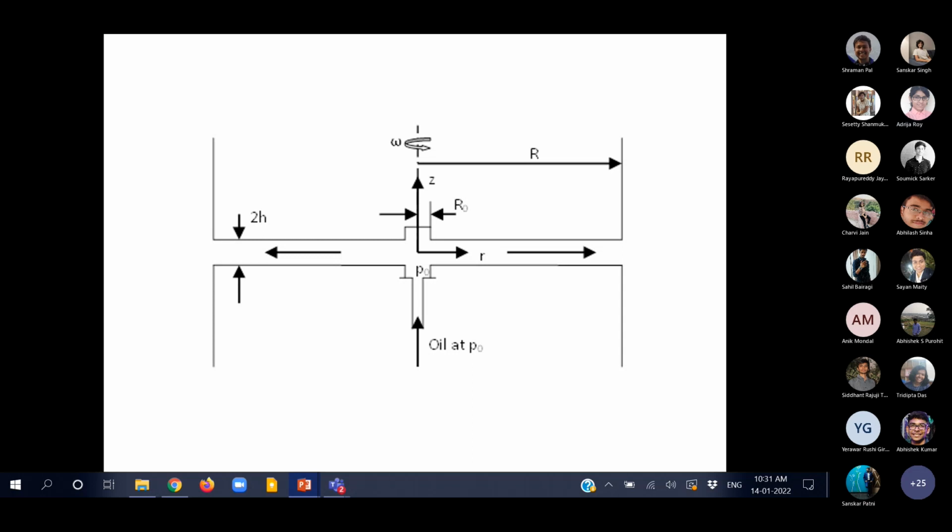For both plates, for the top plate V theta is non-zero but VR is zero. So that is another characteristic of the no slip condition which I wanted to clarify over here. At the top plate, as you have correctly pointed out, my V theta is not zero because V theta is simply going to be equal to omega r or twice pi r omega r, whatever it is.